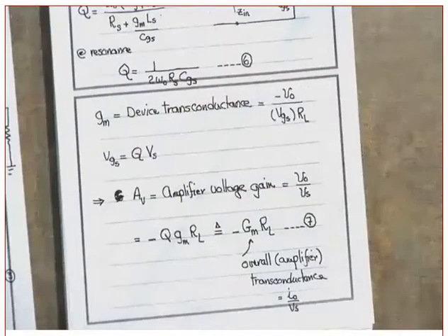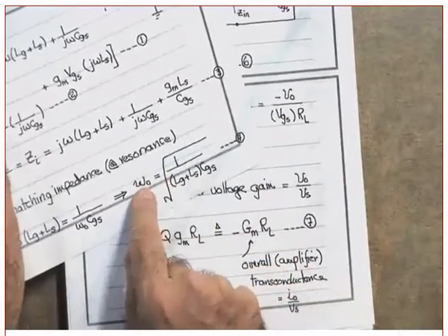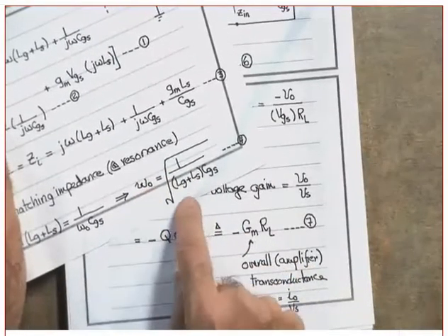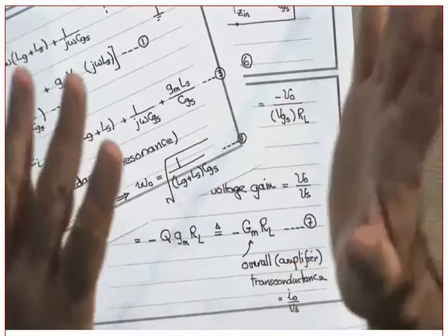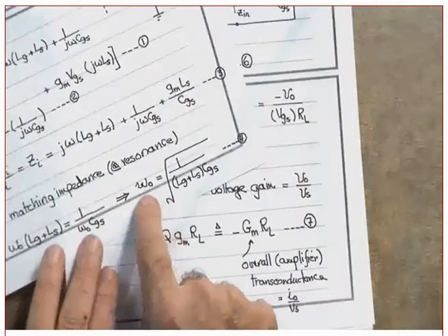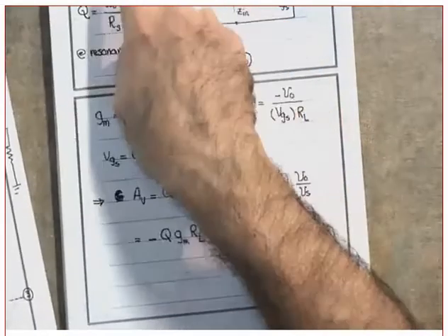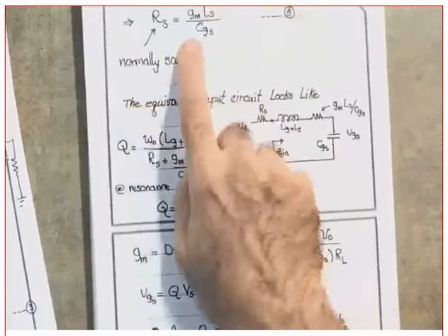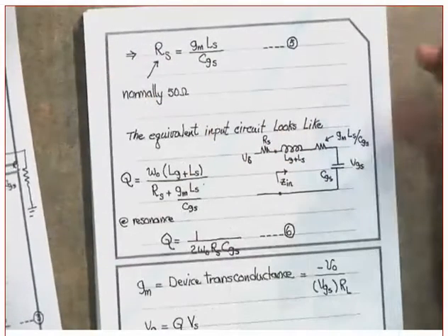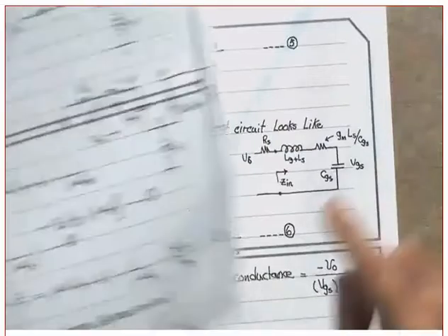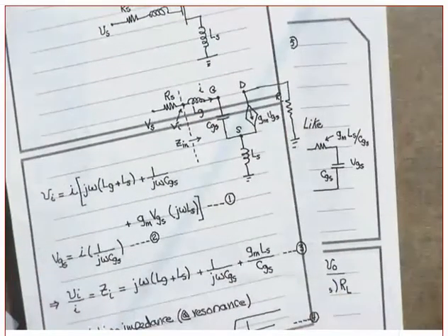I wanted to separate those. In here, by the way, which L is going to determine the fundamental frequency or the resonance frequency? It's the LG, because the LS is much smaller than the LG. So the LG is going to be used to control the value of omega naught. Yes or no? And the LS will be used for impedance matching, for the power matching. Did you get this or not? Yes or no? If you use only one inductor, then you only have one LS to control. Clear?